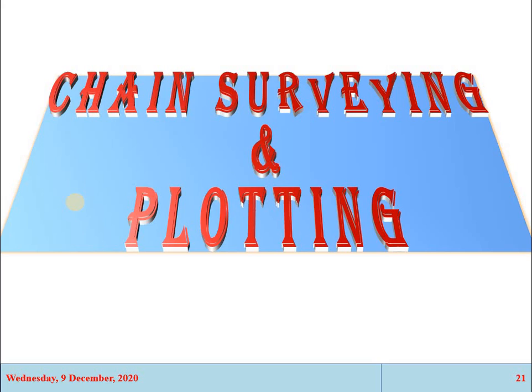Also, we have discussed in the previous lecture that in chain survey different types of equipment are used, like chain, tape, ranging rod, arrows, and cross staffs. We also discussed what a chain is and the different types of chain. We have mainly two types: one is the metric chain and the second is the non-metric chain. Then we have different types of non-metric chain: the engineer's chain, Gunter's chain, and revenue chain. We also discussed the ranging rod, arrows, cross staffs, offset rods, and pegs and plumb bobs.